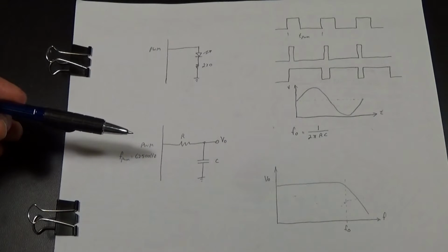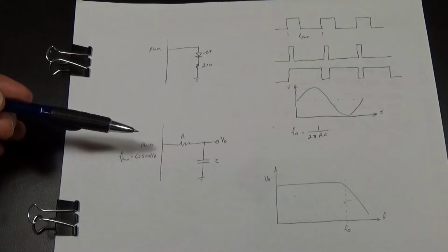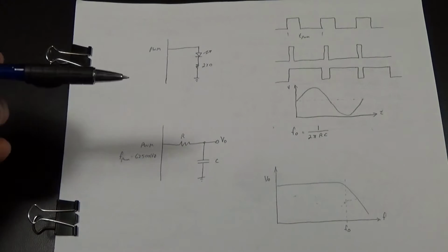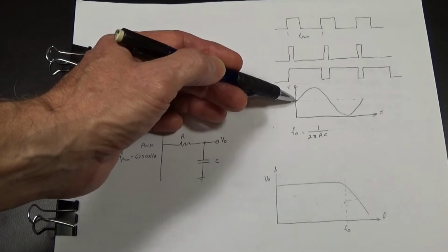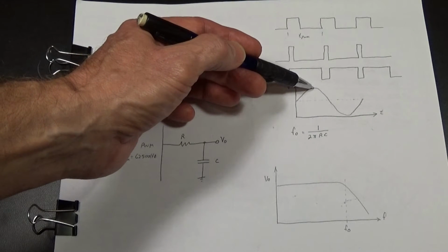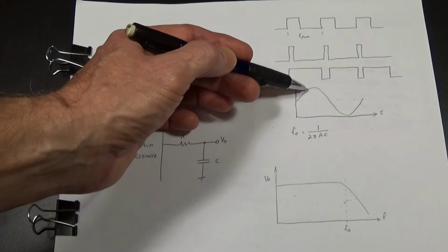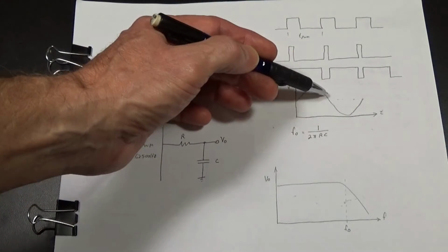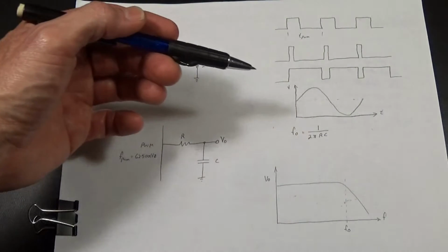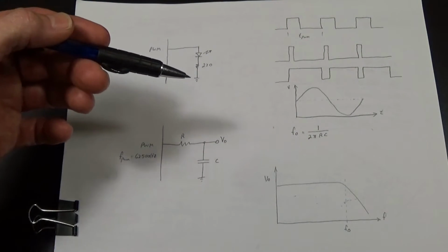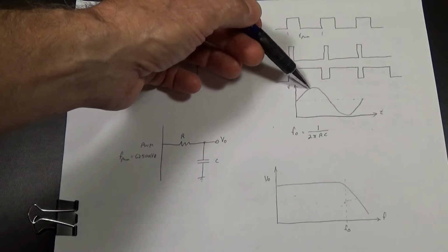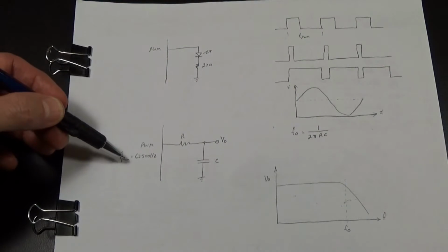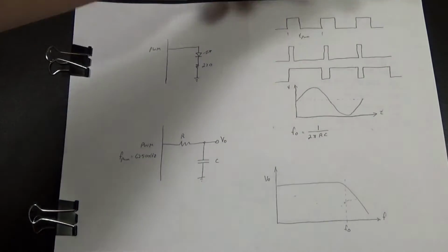Now the method I'm going to describe is called direct digital synthesis, or DDS. You can look it up online, there's tons of stuff out there. And if you remember looking at the software, I had a table that had different values, starting at I think 128 here, and up here was 255, and down here was 0. Those numbers just varied through the table all the way along to give you the different values of the voltage. What I did to generate that sine wave in my first example was I simply read one value after another from the table and output it every cycle of the PWM.